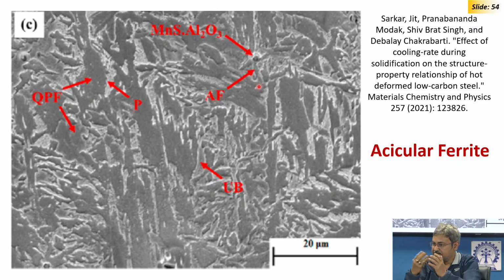So, inside, if there are non-metallic inclusions, they provide a good surface with less interfacial energy and less strain energy, like titanium oxide, titanium nitride, vanadium nitride. So, there it forms, and it can grow like a polygonal ferrite, which we call intragranular polygonal ferrite, like with vanadium nitride. On the other hand, they may grow like a bainite plate, which is called acicular ferrite.